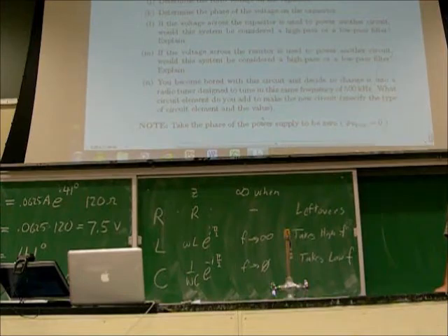Then what would happen is, if it was rainy outside, then the air between the capacitor plates would change its dielectric constant, meaning the capacitance would change and they'd have to go and fiddle with the knob. So on those old-fashioned radios, people were always messing with the knob in order to keep the capacitance value actually being what it was, because the medium in between the capacitor was not vacuum, but it was air, and so as the qualities of air would change, you kept having to retune it.